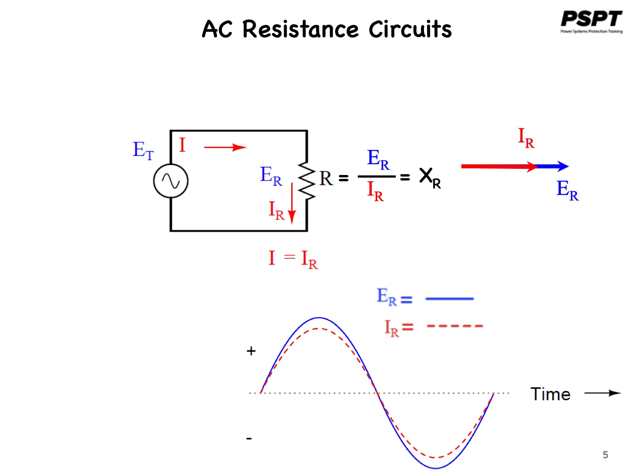And when defined using phasor notation, it is sometimes referred to as the reactance of the resistor and designated as X subscript R. XR, of course, is in phase with IR, as well as the voltage drop across it, ER. In this case, of only one passive element, directly connected across the source voltage, ER will equal ET, the source voltage.